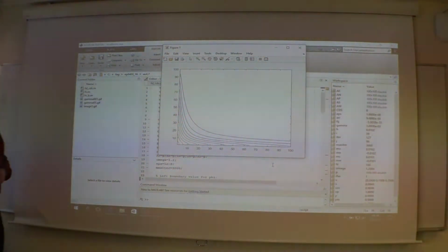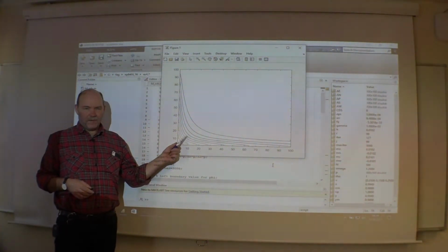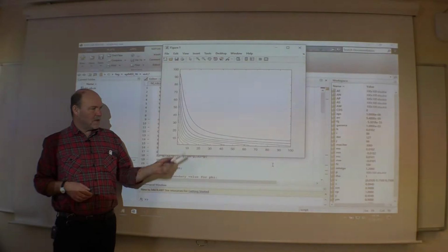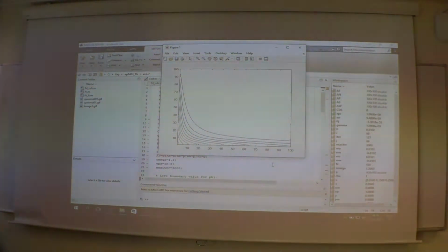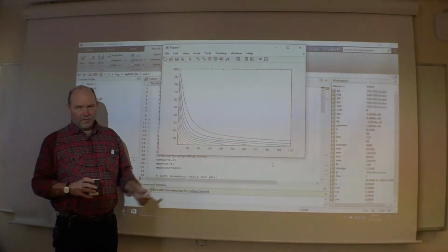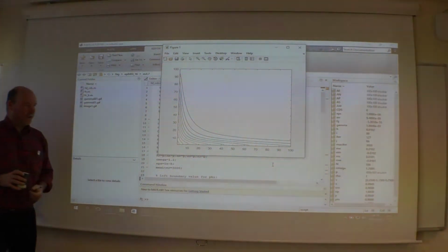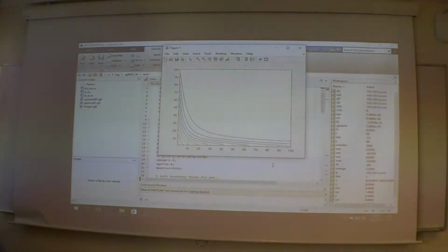So it is not so easy now to tell that this solution from the first order upwind scheme is not the same as the one we had with finite difference with central scheme. That's not so easy to see. It's there. This one is much more diffusive. It transports more phi, unnecessarily far into the domain, but you can't really see it here. You can play around with this one yourself, put these two solutions on top of each other if you like, then you can see the difference.